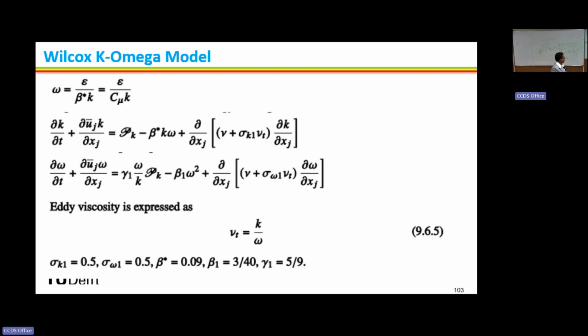So now this is the governing equation. These are the governing equations for Wilcox K omega model, right? So what are the terminologies in this two equation model? Let's find out. This is the K equation. As usual, the left side represents the advection, right? Then this side represents the diffusion, laminar diffusion, plus the turbulent diffusion, right? There are few additional terms. This is the production term, a turbulence production because of the shear. If there is buoyancy, we can add also turbulence production due to buoyancy.